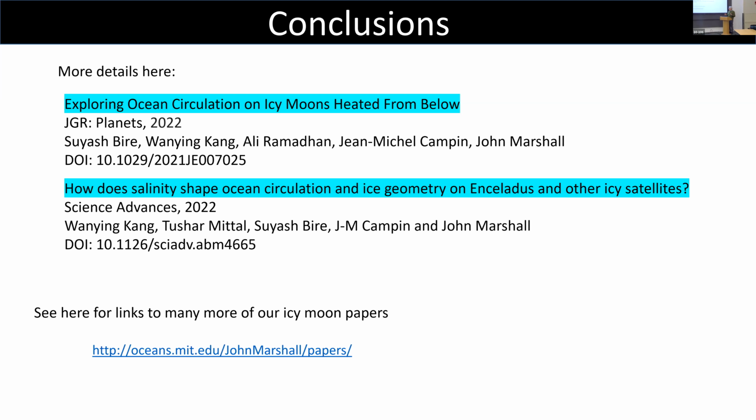there are laboratory analogs that you can carry out. We have a fluids lab over in Building 54, the tall building with the radar on the top. And there are lots of rotating turntables. So if you spin a tank around of about 1 meter in scale with a period of 10 seconds, the typical Rossby numbers you'll get in that tank are 0.1, 0.01. If you're doing self-gravitating spherical calculations, you need magnets and magnetic fluids to kind of glue the fluid on. That's a much harder thing, but you can do flat Earth or flat moon calculations rather well in the lab.